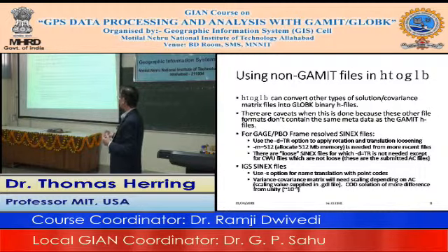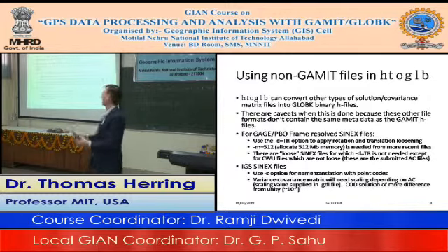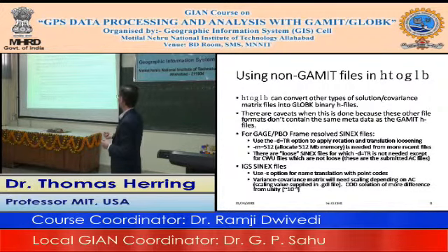There are also sometimes SINEX files that come in what they call frame-resolved versions. These are not loosely constrained solutions anymore. They actually have millimeter-level uncertainty coordinates in them. This is very common if you get them from PPP solutions. For things like the GAUGE and PBO frame-resolved files, and even the IGS frame-resolved ones, there's an option that allows you to translate and rotate to put back into the covariance matrix the uncertainty due to translation and rotation. You do that with an option in H2Global.